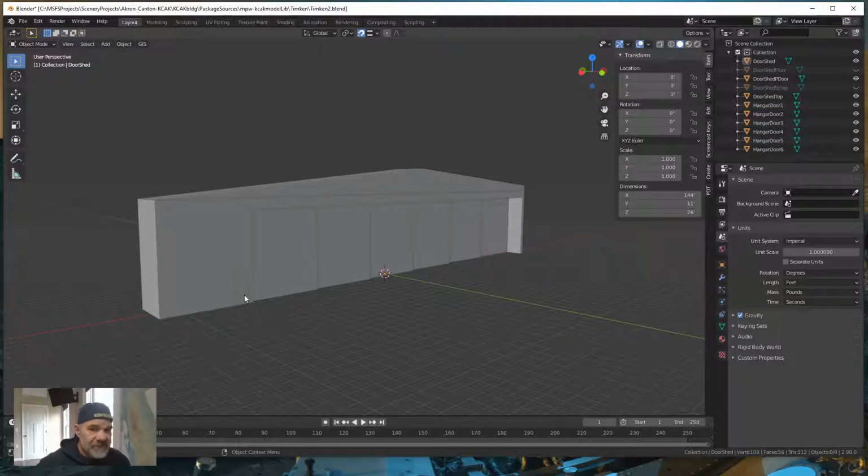One thing about doors depends on whether it opens in or opens out. If a door opens in, the door is inset about 3 to 4 inches. If the door opens out, most likely that door is flush with the wall that it's opening out from. Okay, that's just standard construction, with the exception of maybe the trim around the door, but we're not talking about that right now.